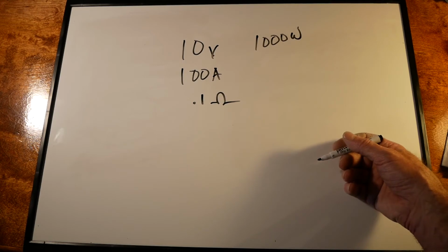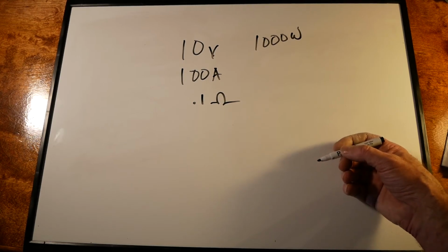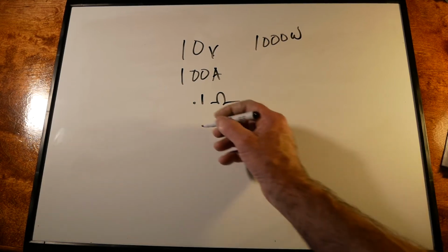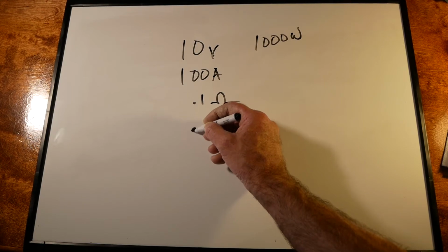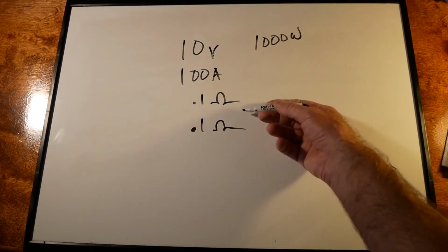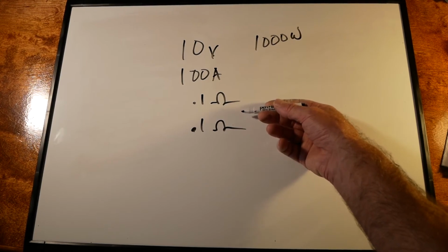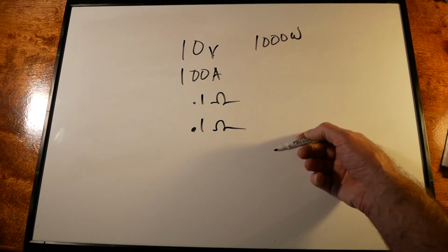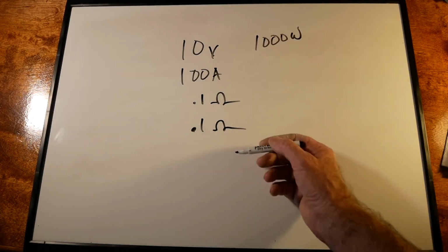Let's say that you had a battery with corroded connectors, corroded terminals, and the connection between the terminal and the battery cable has severe corrosion, and where the eyelet bolts to the starter is corroded, and the total sum resistance of all that corrosion is 0.1 ohms. What you've essentially done is you've cut the power going to your starter in half, because at each one of these junctions we're going to drop the same amount of voltage. So without this,